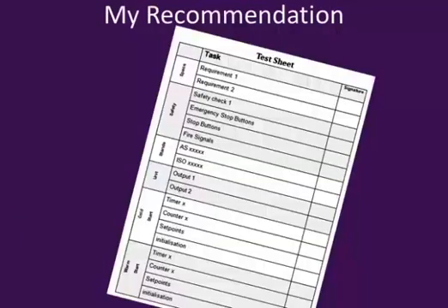What I recommend is a combination of the methods above. I prefer signature sheets to check sheets because they're harder to forge. You check it performs according to the spec. Check it does all the right things in a fire or after an emergency stop and time schedule events.